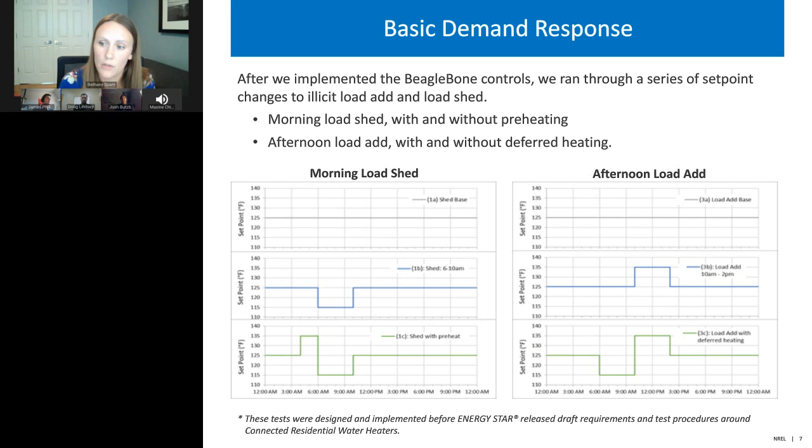And then on the load add side, something similar. Our basic load add was increasing the set point for 4 hours in the middle of the day. And then the advanced was having a period of time where the set point was lower to try to defer heating until that load add case.